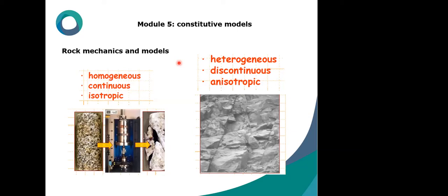However, it should be said that it does not mean that tunnel support in rock is more costly in comparison to soil tunnels. Generally, in most cases, tunnel lining in rock is lighter, even though there are points that should be taken into consideration in the design of tunnels in rock. I will try to present the methods that consider the rock specifications in the design process. First, we should know these specifications. Afterwards, how to convert a discontinuous rock model to a simple continuum model that considers most of its specifications.